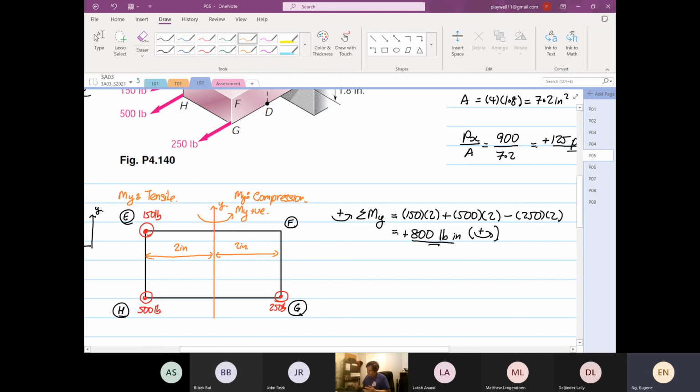At the same time, you can also calculate Iyy. Some of you are like, oh shoot, how do I know what is Iyy? Which is your width and which is your depth? Not to worry: parallel to the axis, this is your width. Perpendicular to the axis, this is your depth. Simple.